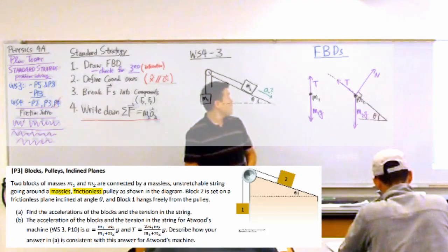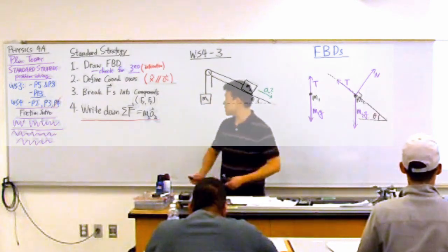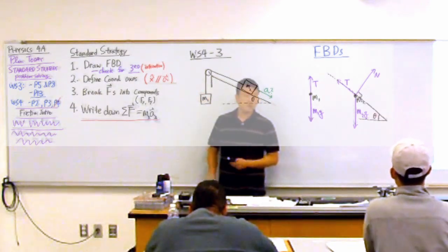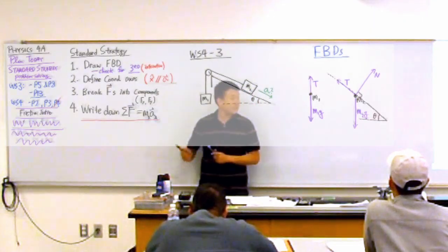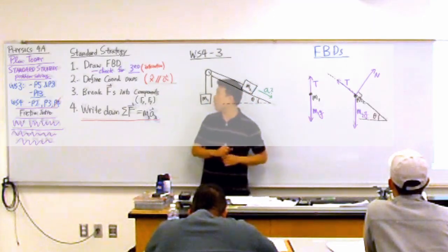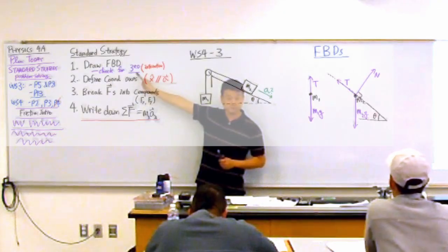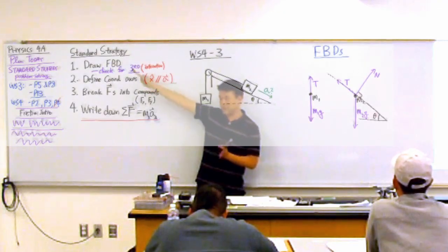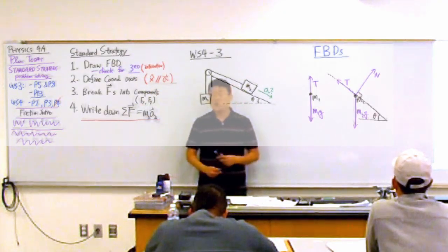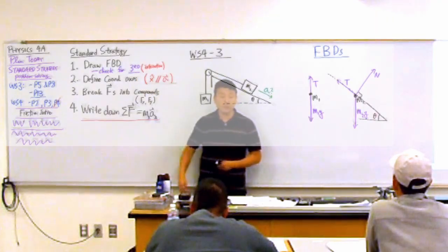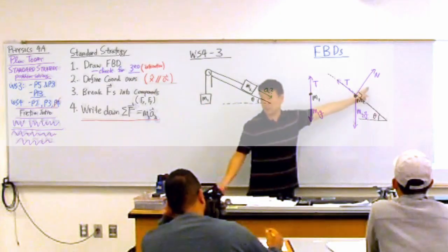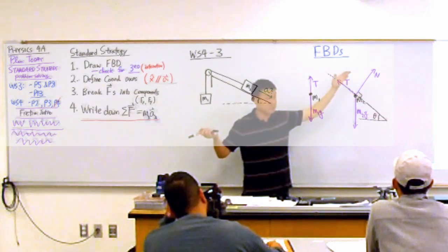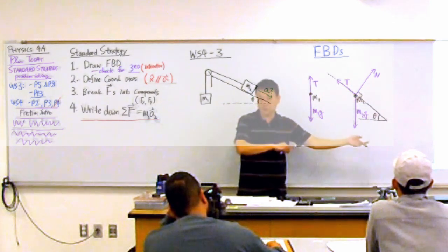Okay? So we are done with step number 1. Wait, we're not done yet. We are almost done, except because I have two bodies, now I should check Newton's third law. This should be a habit that you always check. With this check, we make sure that every one of the forces we have drawn is either an external force or an internal force, and here's where the reaction force is.